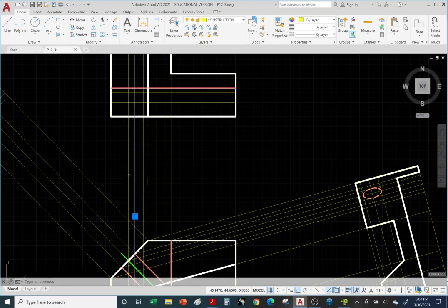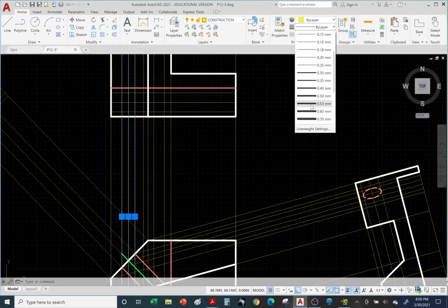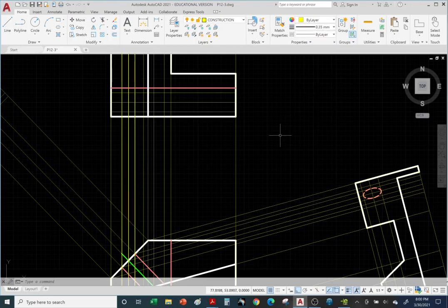These construction lines and this construction line will define our center mark and our diameter for the hole, our quadrants. Let me make these a little bit thicker so they stand out a bit. There they are. Hit escape to deselect.